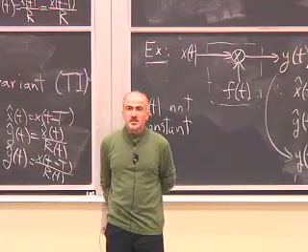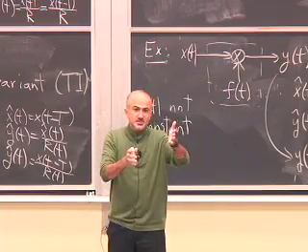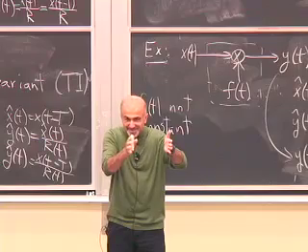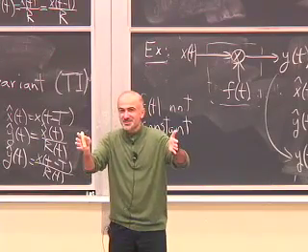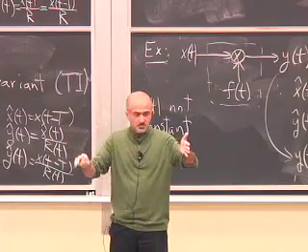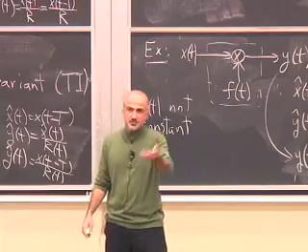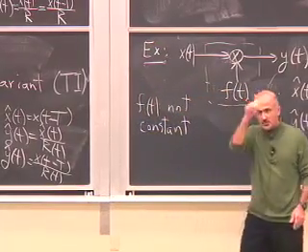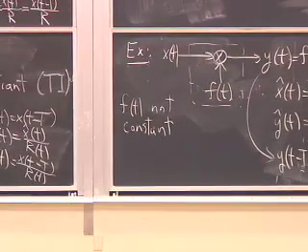If the capacitor has an initial charge at time 0, if I shift the input signal, the portion that is due to the initial charge doesn't get shifted. So you can imagine the system is not time invariant. But if the capacitor has no charge, then clearly if I shift the input signal, the corresponding output signal will shift. And you'll work through this, the actual integral that relates the current and the voltage of a capacitor, in a problem set. Yeah?